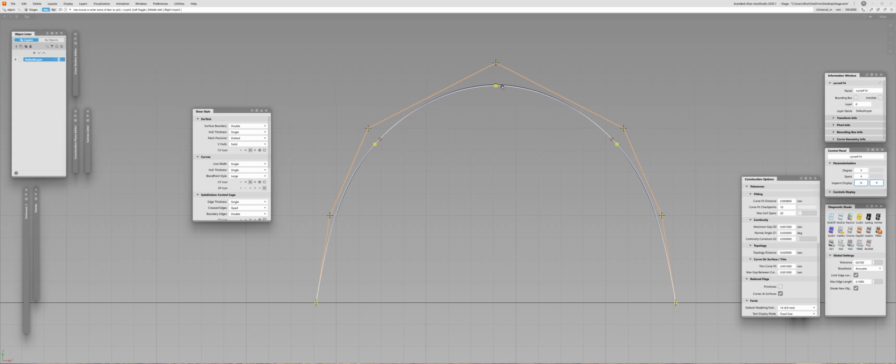Another big problem with chordal is that chordal butchers your internal structure. So in the uniform parameterization, if you create a revolve, a surface, and you divide it by the U and V directions to create some parametric pattern on top using Grasshopper and Dynamo, you will have no issues. But if you have chordal instead, this spread will be non-uniform anymore. The curve will be great, and the surface from that may be great as well, but it will be really difficult to uniformly place something on top of that.